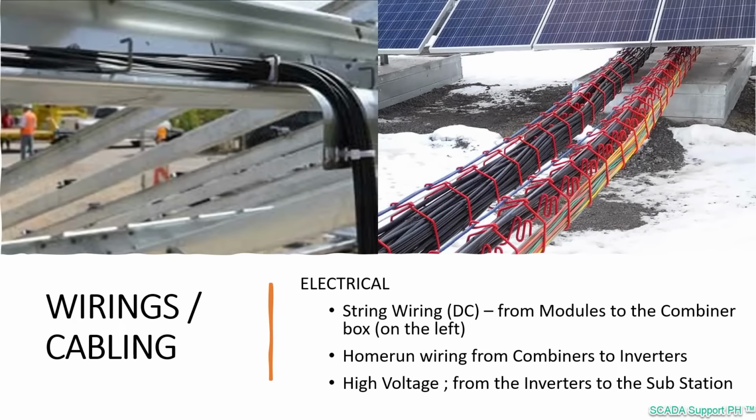When we look at the power plant overall, we can see different types of wiring. In this example, we have the electrical side that carries the electricity. The lowest level of electrical wiring is the string level. Usually there are 10 to 25 modules within a string, and the wires from the modules are connected in series, meaning you have the same current.